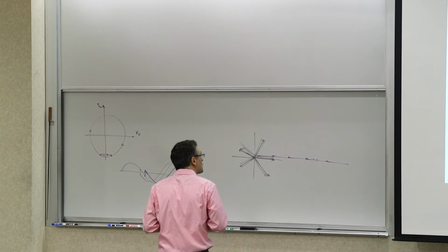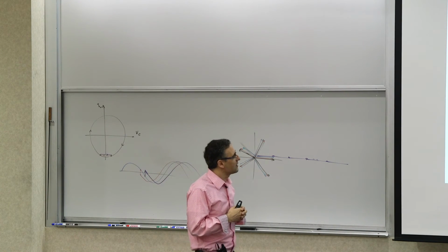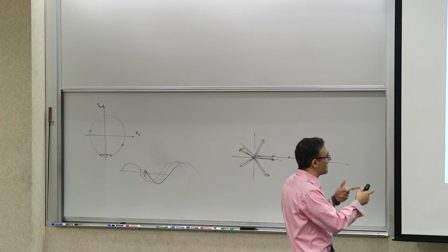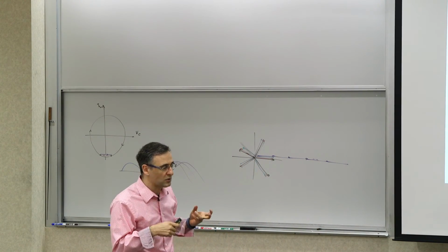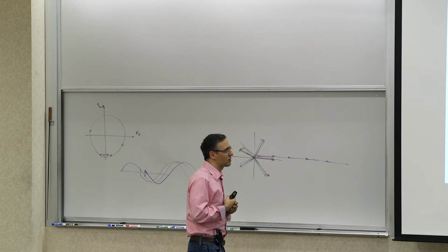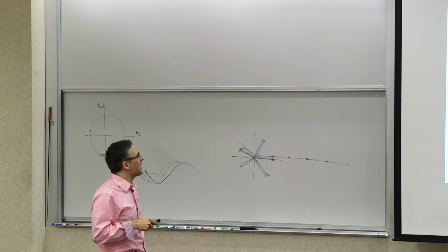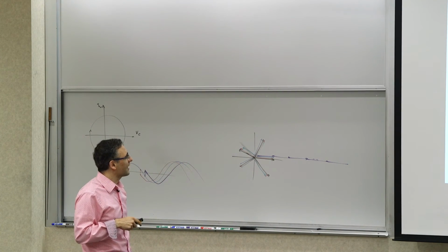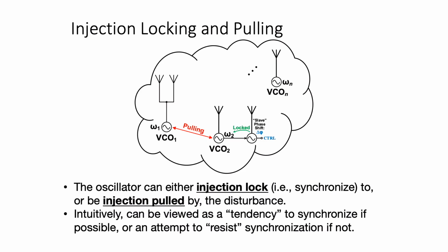also be applied to injection locking and injection pulling. We are going to talk very briefly about the work of Brian Hong, which has applied the time domain viewpoint to the injection locking model of oscillators. Think about multiple oscillators that are in the same environment and communicating with each other. They can actually start locking to each other or pulling each other.